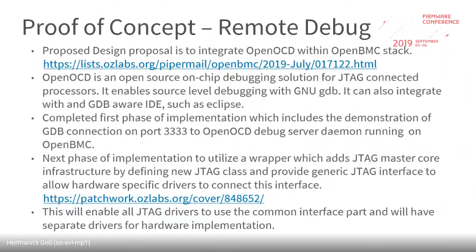The next phase of implementation is to utilize a wrapper which adds JTAG master core infrastructure. We were looking at some of the patches which were present in OpenBMC. We are pretty sure that we can reuse one of those, and we will provide our own hardware-specific driver to connect to this interface.